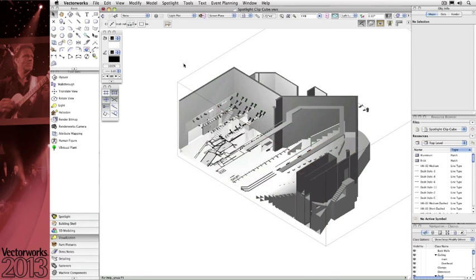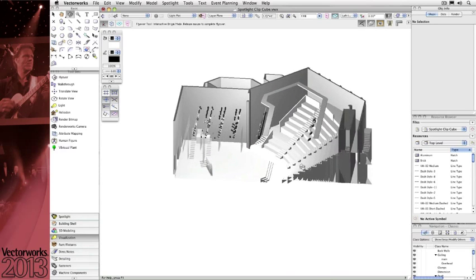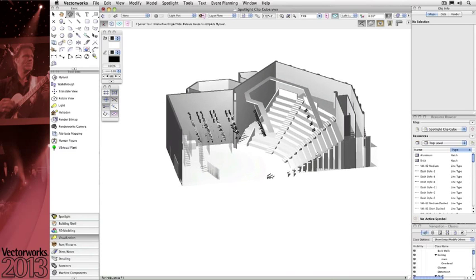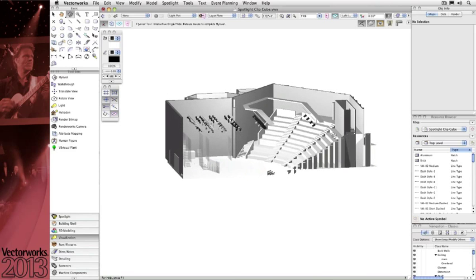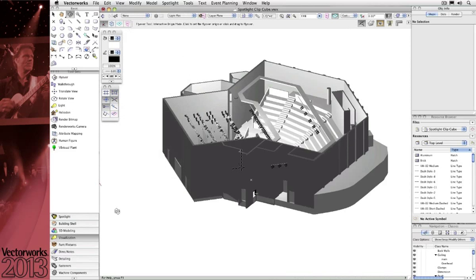When the tool is activated, a bounding cube is created. Any face in the 3 axes, X, Y, and Z, can then be used to dynamically cut through the model. The model can be viewed in either orthogonal or perspective projection, and in either wireframe or OpenGL rendering.